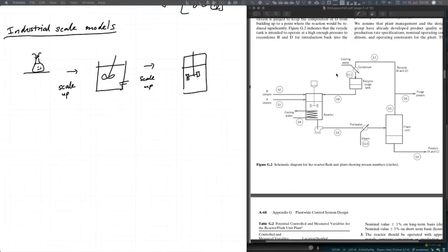only steady state. You definitely wouldn't do a dynamic model in most cases, and so part of the plant is built from experience and part of the plant is built from steady state models. But you can imagine that the steady state model, for instance, doesn't even include sizes for these vessels. So we don't know necessarily what the correct operating level should be or what the effect of the level is on the rate of cooling or anything like that. So there's a lot of stuff that we don't know by the time we put together the model.